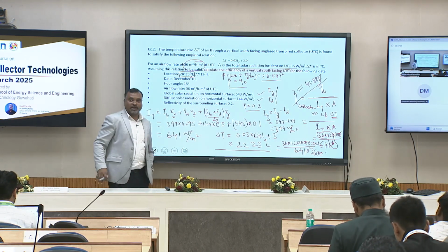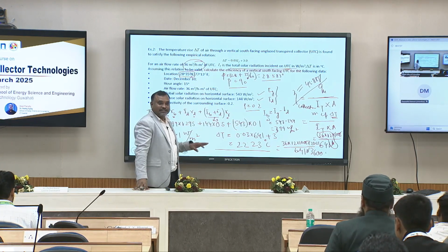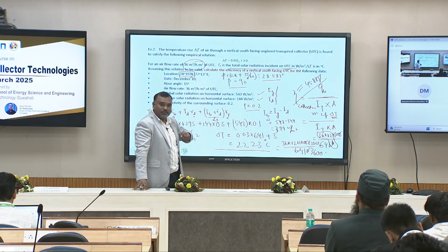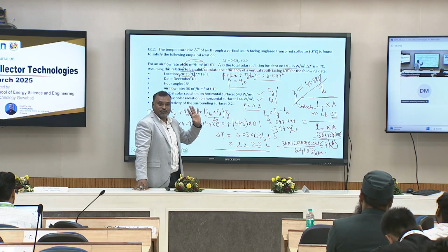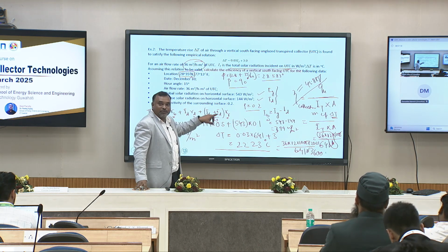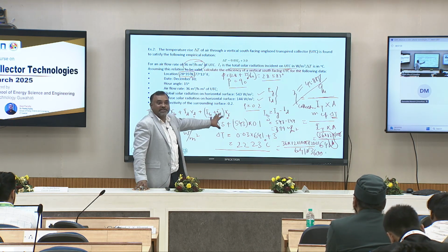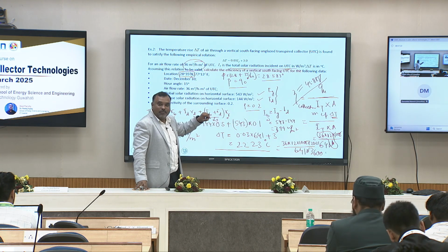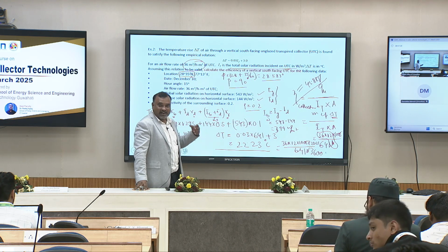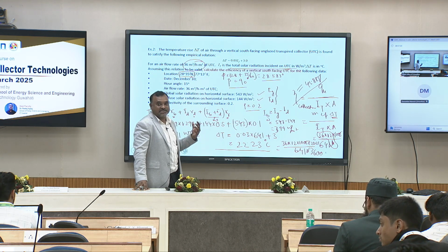It's quite an interesting problem, right? We just gave some input parameters. It's a solar air heater. We gave some amount of volume flow rate per square meter, and then we have included all the analysis. That's why I picked this example. So now, just recalling the expressions, what is RB, what is RD, what is RR, and why these expressions have come into consideration.